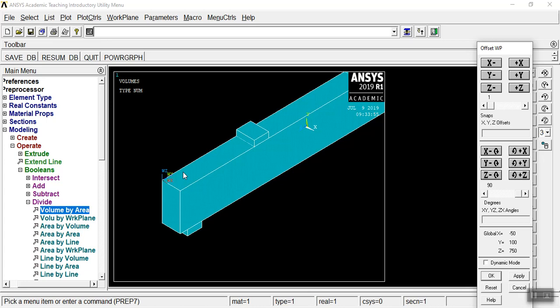Now I should move it down 20 millimeter to make the cover. So this will be down 20 millimeters to make the cover of the beam. So in this part we can write 0, then minus 20, because it's against the Y axis.